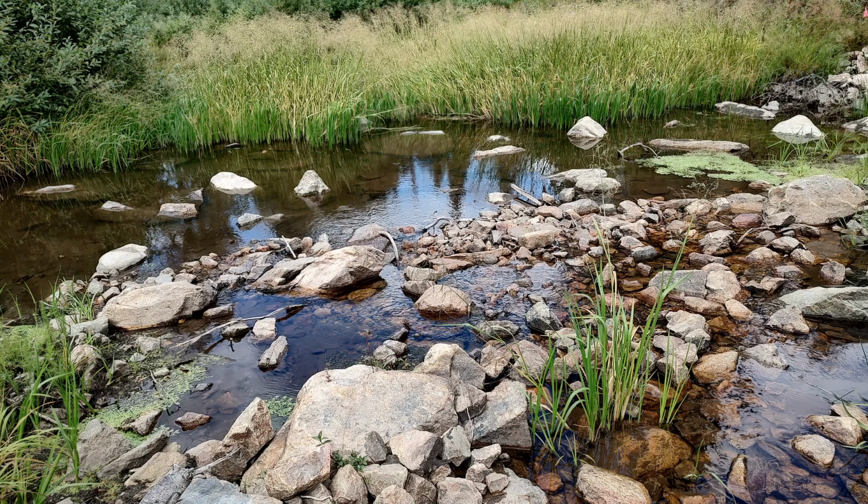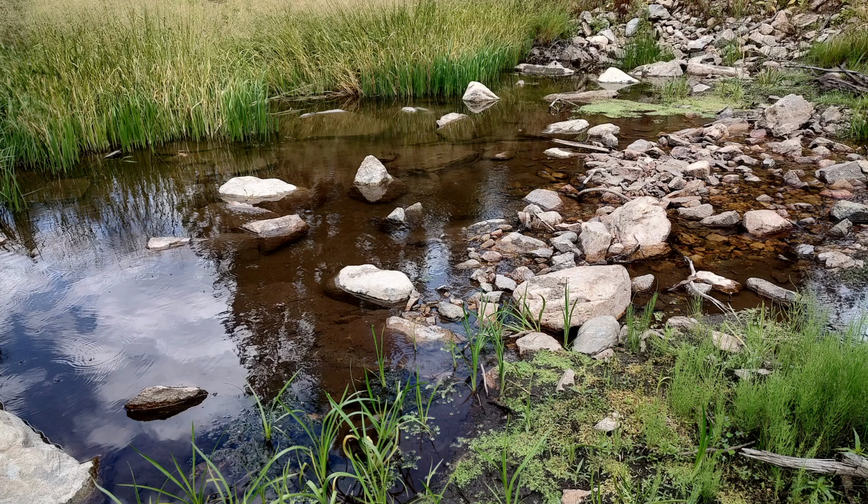Here's where we controlled a head cut in a stream following the removal of a dam near the community of Trail in British Columbia. We placed rock from a quarry in the trench and then covered this rock with natural-looking creek rock. We made this riffle on top of a buried vertical grade control structure that we built to control a head cut in the stream, also in British Columbia.